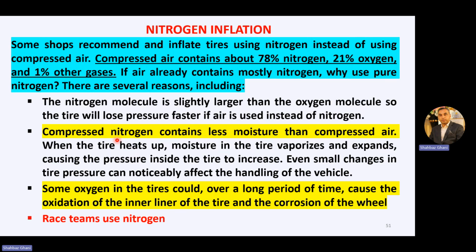So compressed nitrogen contains less moisture as compared to compressed air. When you are moving the vehicle, the tire heats up, and the moisture vaporizes and expands, causing the pressure inside the tire to increase.